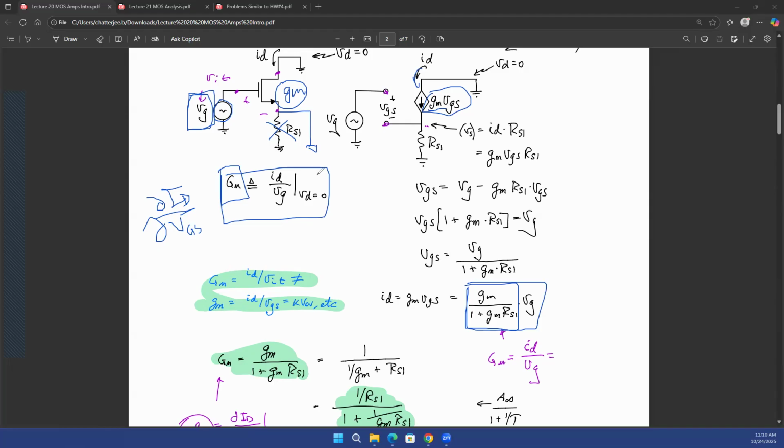Yes. So that circuit on DC might actually have a +7 and -7. Exactly. We can't see that. We are not interested in that anymore because we are doing AC analysis now, and we're assuming that the DC analysis is already done and the transistor is in saturation. See, one other indication is that there is a ground over here. So that's an AC ground.